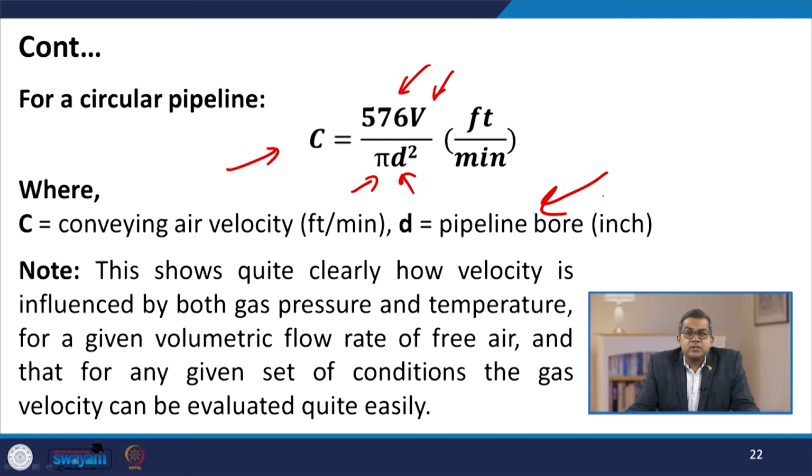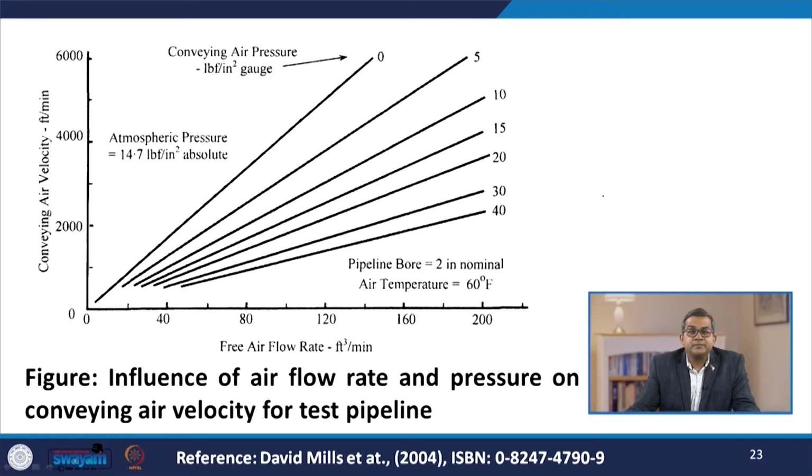Now this shows quite clearly how velocity is influenced by both gas pressure and temperature, for a given volumetric flow rate of free air, and for any given set of conditions the gas velocity can be evaluated quite easily.